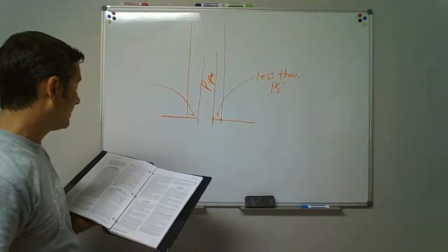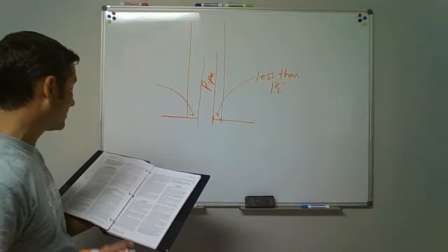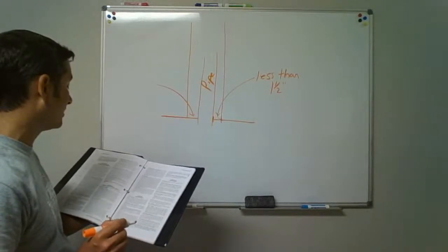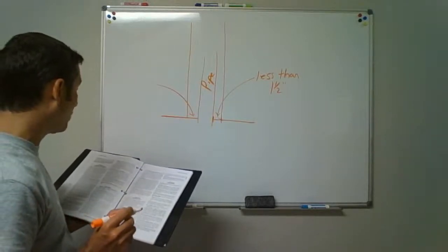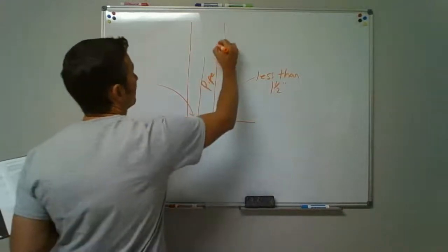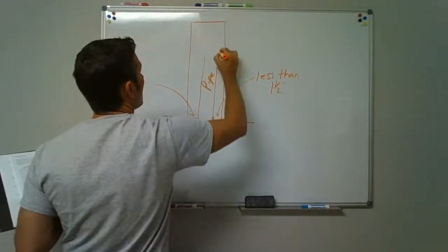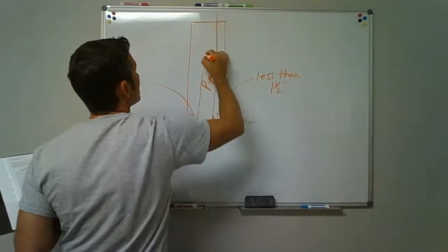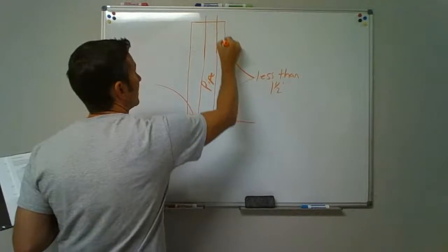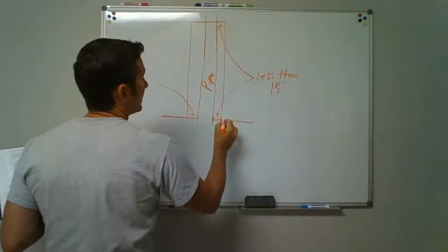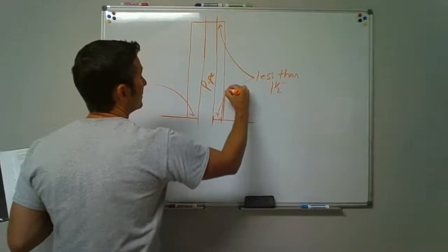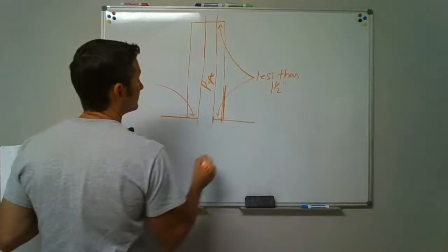Okay, it says such plate shall cover the area of the pipe where the member is notched or bored and shall extend not less than 2 inches above the sole plates and below top plates. So if this is the top of the wall and the pipe goes right up through to the attic, we've got to put a plate here. Now this plate gets nailed to the side of the stud.